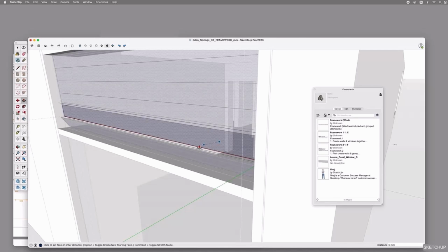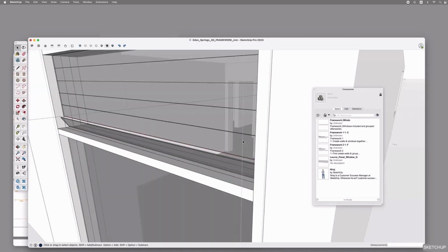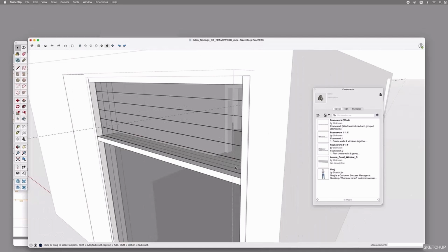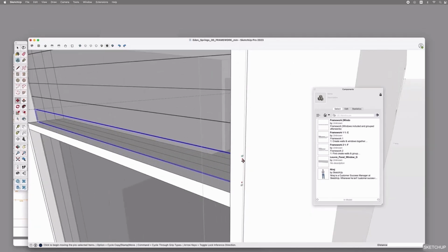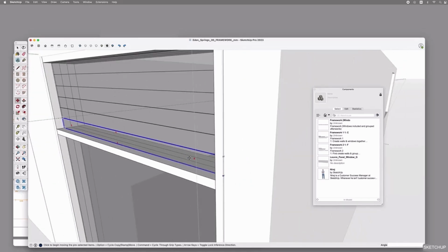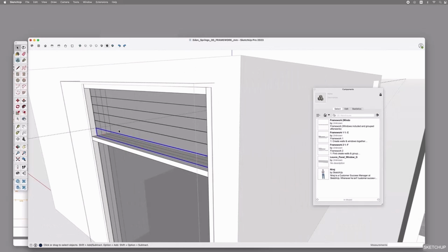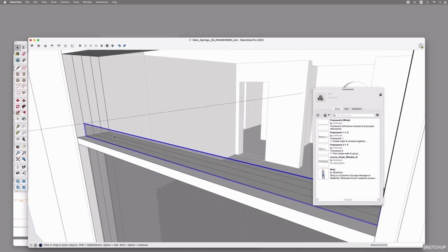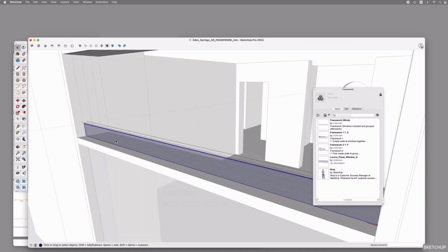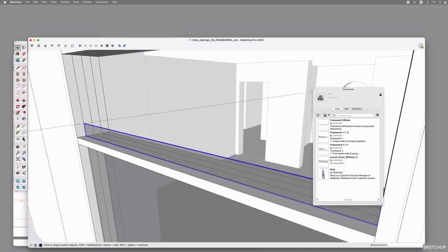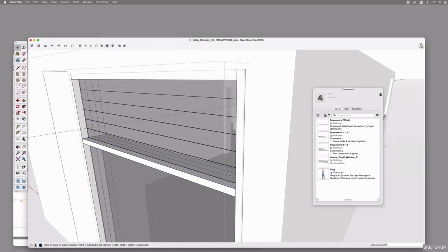While it works changing the surface, rotation doesn't work, merely because SketchUp needs to know the direction that is applied to it within its component. So right now, you kind of rotate the outside shape. In order to be able to rotate all clones simultaneously, you need to create something that SketchUp can work with. So before we copy those component panels, we have to go inside our component, create a group within its environment, leave the component, and then start copying the panels.